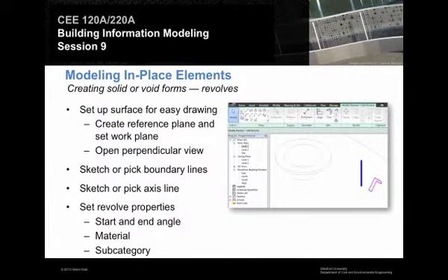Another really useful one is called Revolve. With Revolve, you take some sort of profile, you take an axis, and you just spin it around the axis. It's like if you've ever used a lathe or some sort of tool to spin a surface around something. So this axis and that profile created that whole shape. It would just spin it around, and that's also very useful.